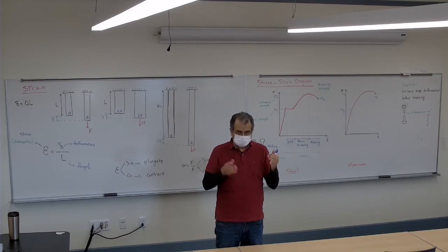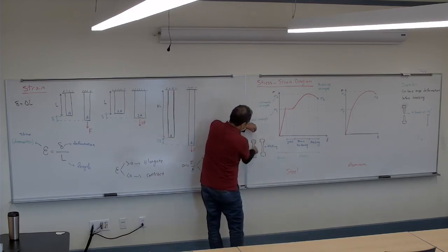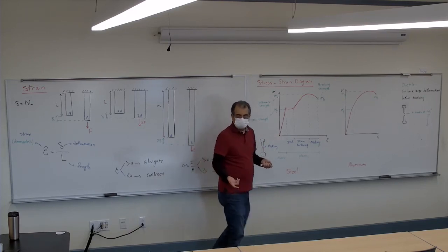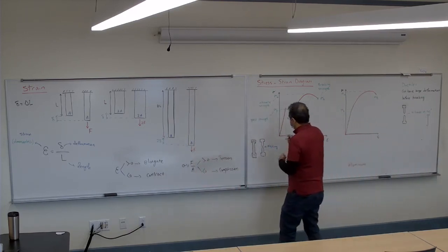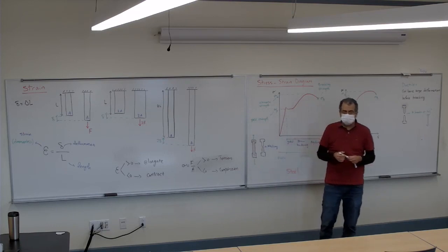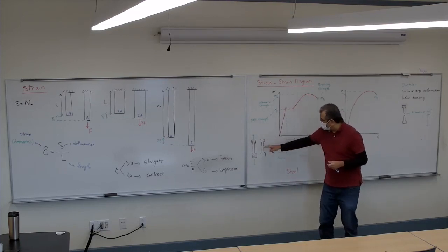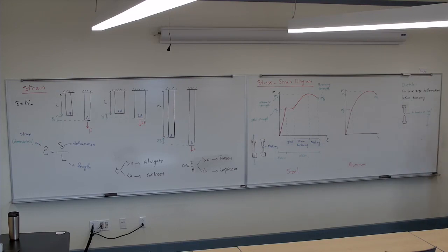Shear becomes maximum at 45 degrees. Because look at it, if I put the force on that, it's a completely axial force, correct? So basically what I have here is just axial force pulling it. Under axial force, I get the 45-degree break. On the axial force, the shear becomes maximum at 45 degrees.